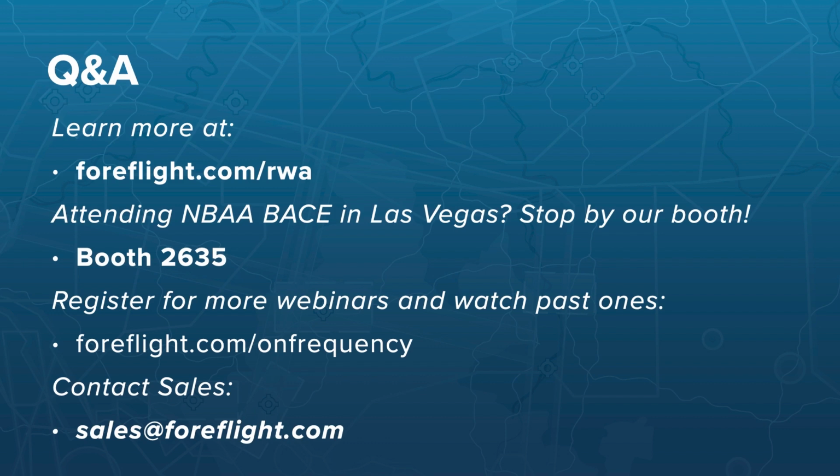I do. So the answer is that yes, you can select your defaults. The defaults are primarily set from the more menu in your aircraft profile under your runway options. And as an example, in the case of the Challenger, some of the options that you can set defaults for would be whether APR is armed or not, 10th stage bleeds being open or closed, rolling takeoff, those sort of things.